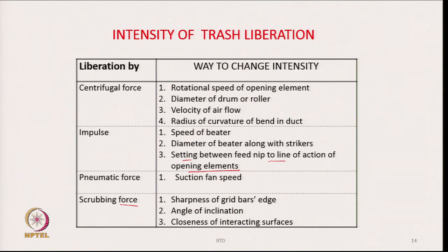The other phenomenon is pneumatic force, which depends upon the velocity of the air flow. The velocity of the air flow depends upon the discharge rate of the suction fan, which in turn depends upon the rotational speed of the suction fan. And the scrubbing action